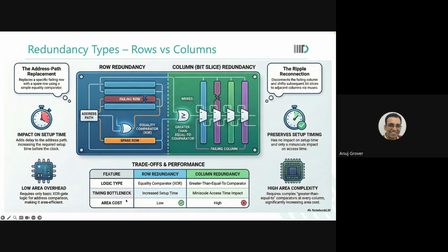Now, since my output is going to be 1, the next one will also see that, oh, this output is 1, meaning I also have to shift. Then the next one, oh, my left neighbor has 1 as an output, so I also have to shift. And this ripples. So what that then does is, you save the area, but you've taken a hit on performance. Which performance?